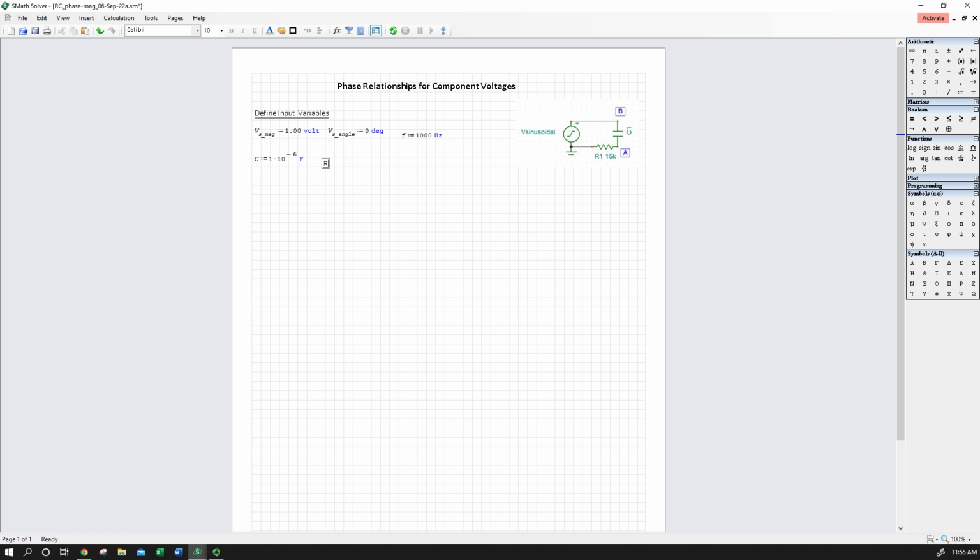So I'm going to go ahead and define a magnitude and angle associated with that resistor, which is not going to change with frequency. So I'm going to define it up here. So I'm going to define R as a magnitude. R, and I did the period to give myself a subscript. Magnitude equals, and we're going to start with, let's go 12 times 10 to the third. So a 12K. And I want ohms, so I'm going to bring up units. Ohms resistance. Here we go.